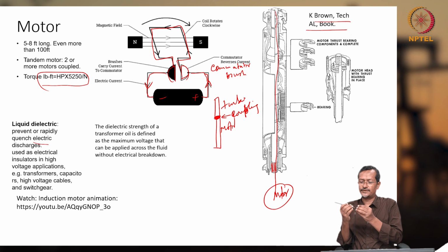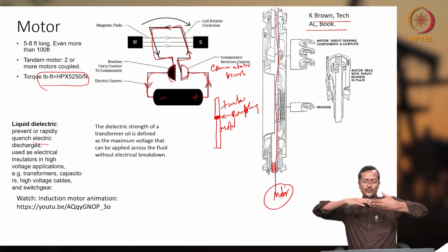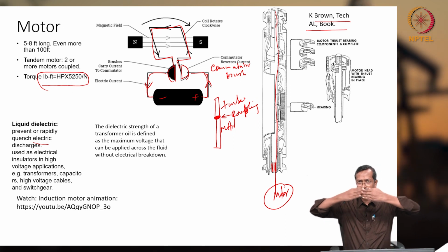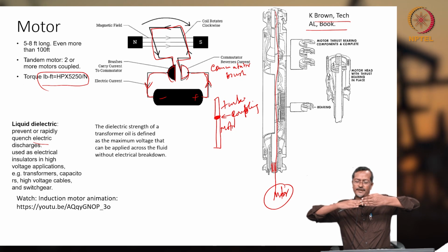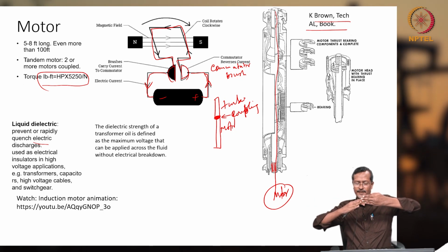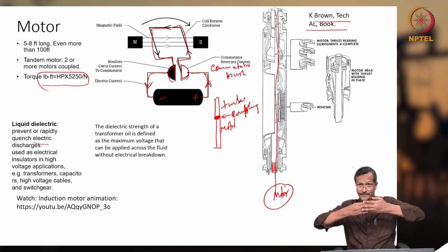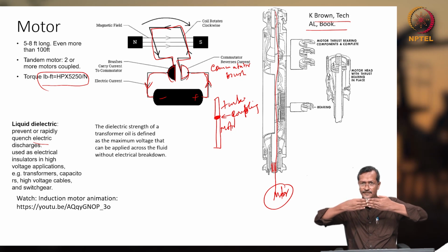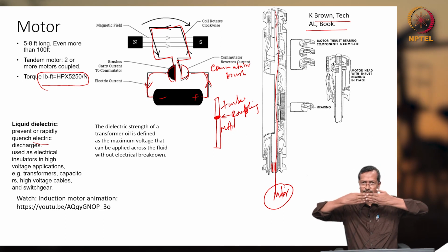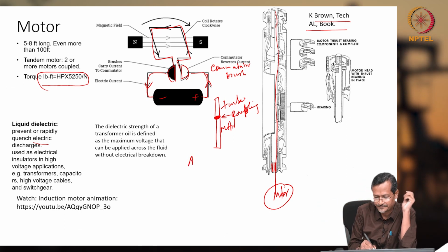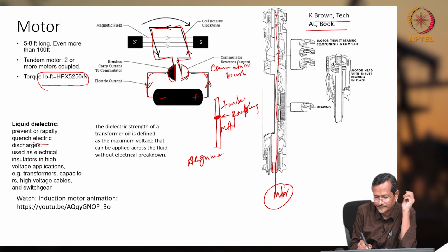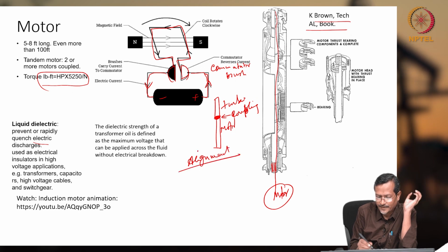So you cannot make this joint between the two shafts very strong. If you make it very strong, then if there is any bend, it will try to rotate but it is not rotating because of this bend. So you have to give some flexibility, axial flexibility, so that if there is any misalignment, the alignment issue won't be a problem. Okay. Alignment, how to do flexible alignment.